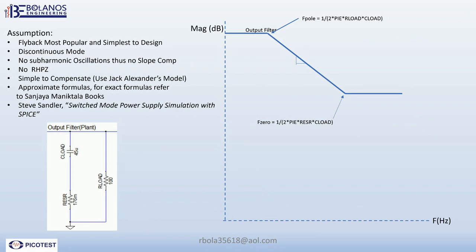Here are my assumptions. In this case, I've designed a flyback, and flybacks are the most popular and also the simplest type of switch mode power supply to design. I'm using discontinuous mode, and the reason is it simplifies the design by not having subharmonic oscillations.